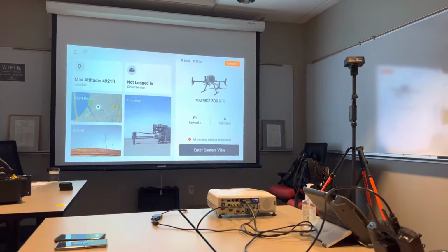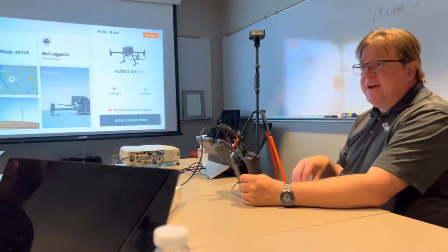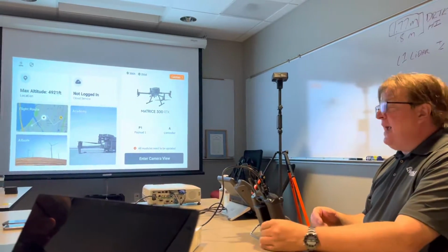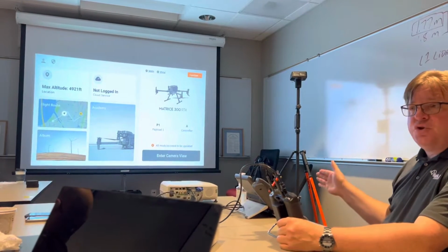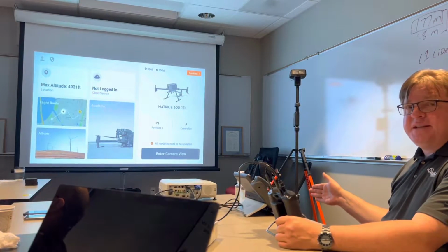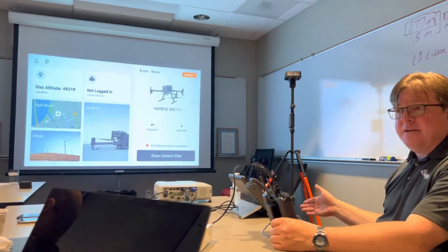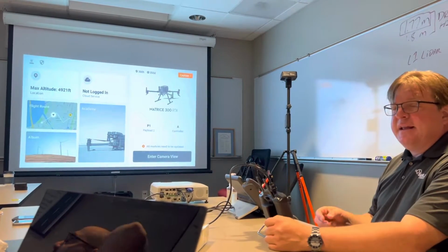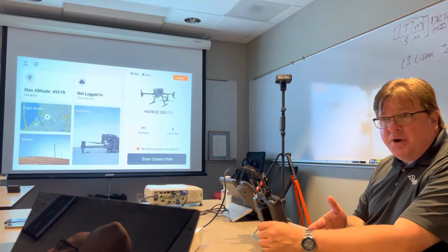Survey operation, you're going to create a fixed known mission, okay? So this is back at the main page. When you're on site, the first thing you're going to do is turn the drone on so it can start collecting GPS data to identify where it's at. When you start your flight route mission planning, the map will be the first thing that pops up, and it's going to zoom in right where you're at.